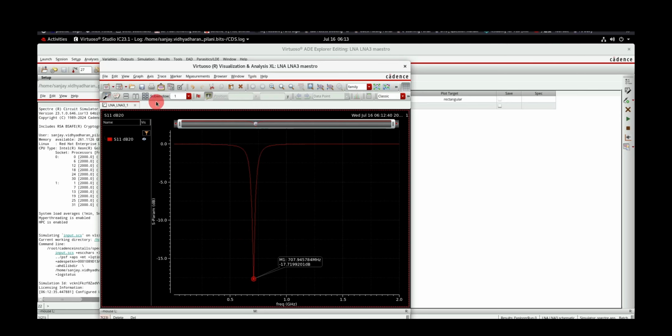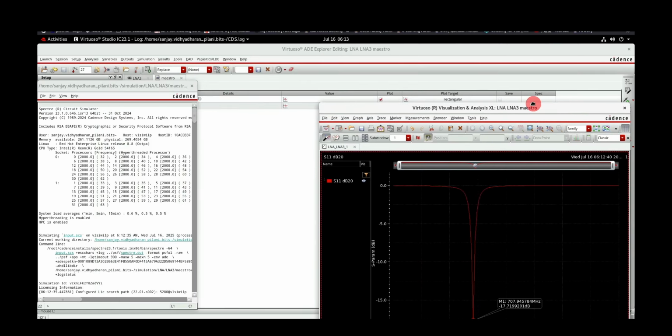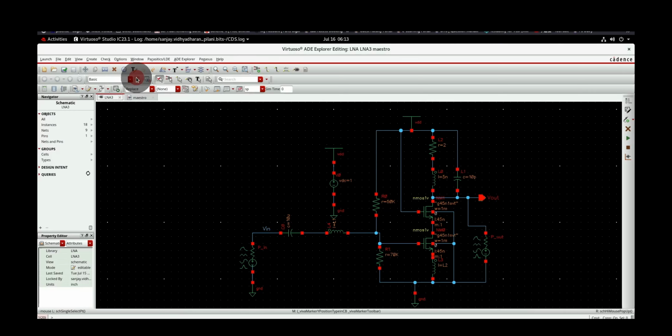So now what I have done from the previous circuit, if I go here, is I have inserted these two inductors and ensured that the maximum power transfer condition is met. So maximum power from here is transferred here, and hence very little reflection is happening. Now when you put these two, you have to be careful that there could be some loss of gain here.